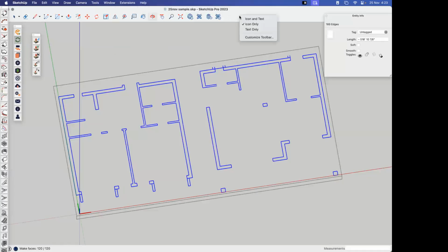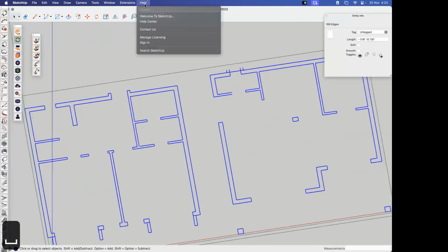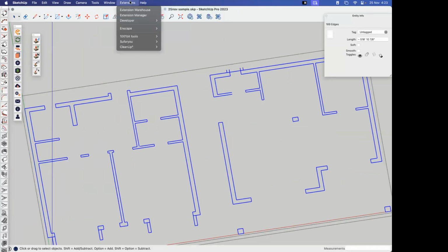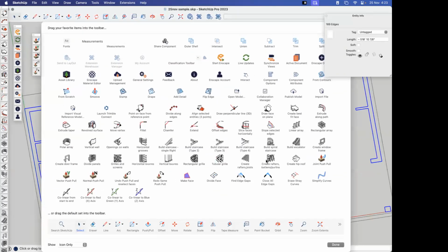I'll add the edge tool, because some of the polylines explode in SketchUp when you import a CAD plan. That happens because CAD and SketchUp are not designed mainly on the same platform. And in CAD, it's difficult to create groups and hierarchies which are again usable in SketchUp. So the best ideal way is just to drag and drop all of them. So I'm going to add the extension that we just installed called Edge Tools.